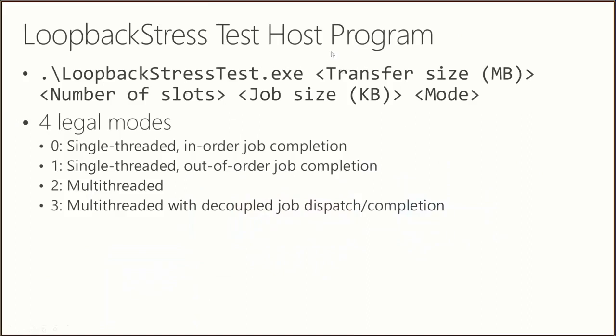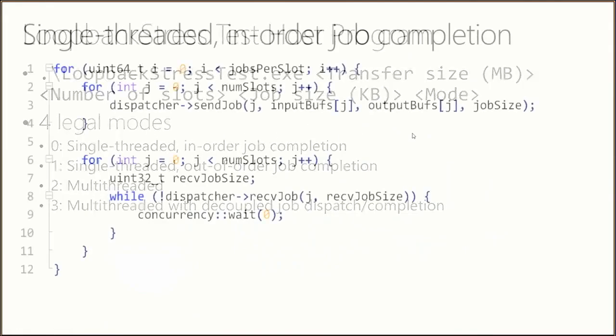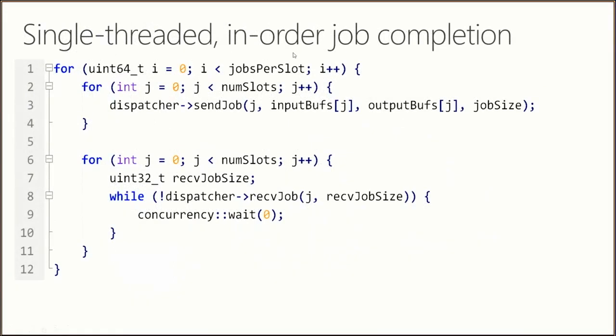The loopback stress test host program is a host program for the PCIe loopback stress test and the DRAM loopback stress test. To run it, you simply type loopback stress test.exe with the transfer size in megabytes, number of slots, job size in kilobytes, and the mode. There are 4 legal modes.